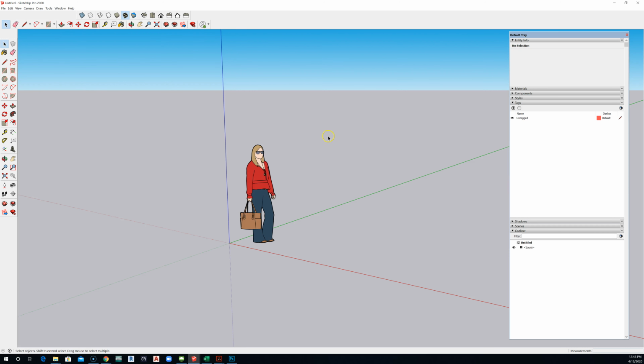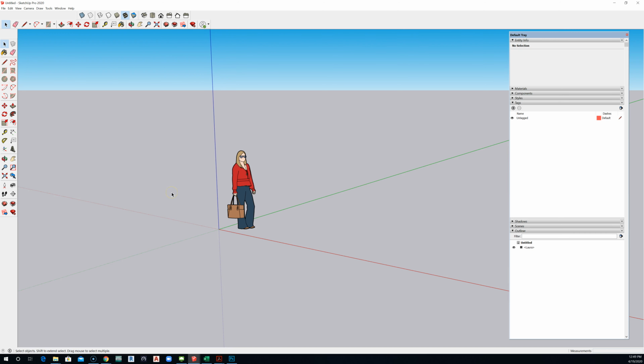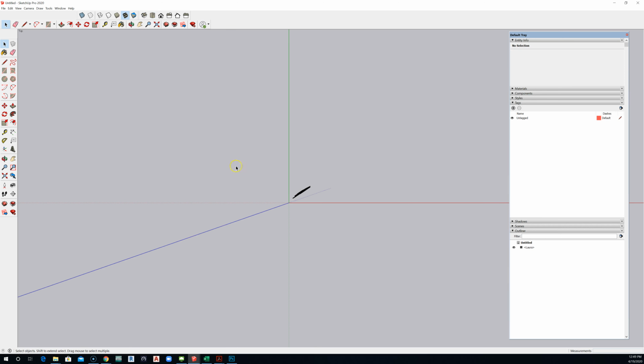I'm going to start a new project. I'm going to use the same two-story building. This time I'm going to begin drawing from scratch, but instead of using an image underlay, use an AutoCAD underlay as the basis for my model. So I'm going to go to a top view, and whenever you're doing things like this, you should work with the camera set to parallel so you don't introduce a perspective distortion, because you're trying to measure things. And you want to give axes equal weight.